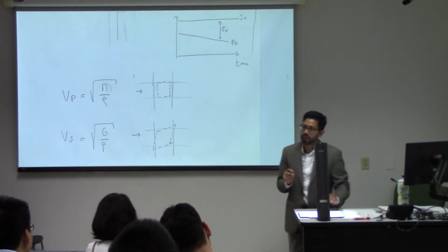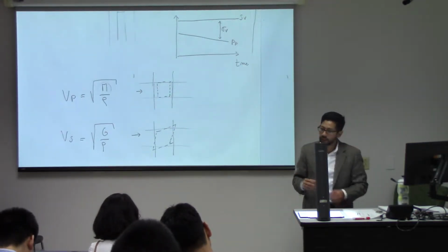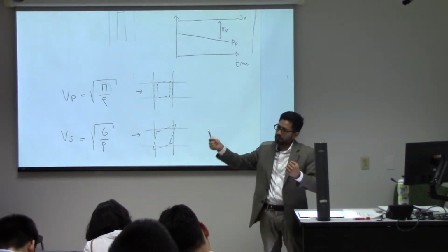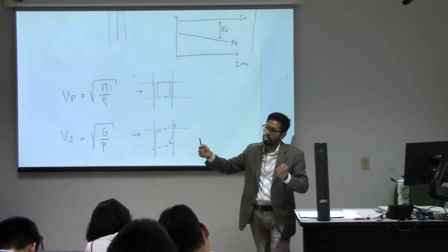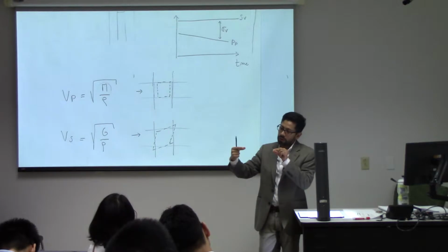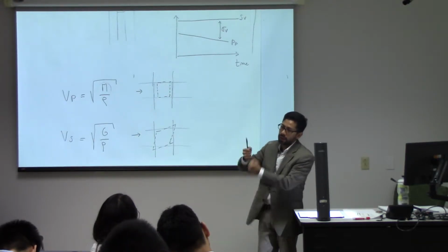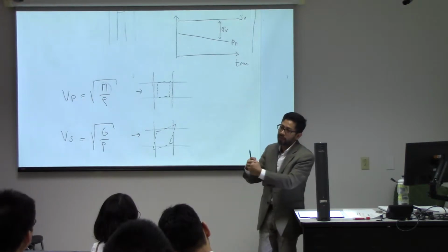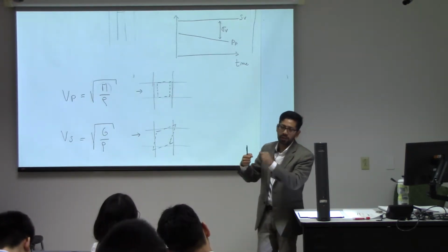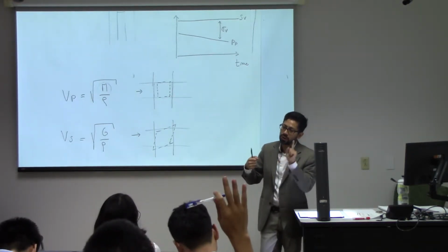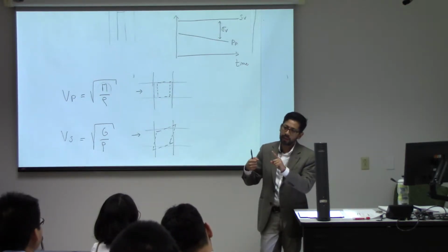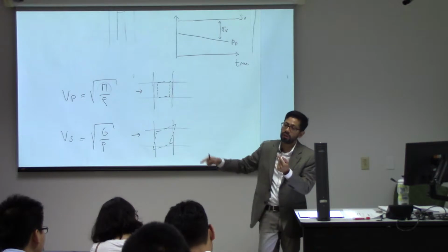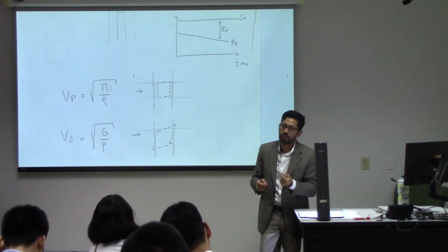That's another thing. For example, if you have a long rod that you hit with a hammer on one side, the rod is going to be able to expand to the sides, right? Like the same test that we did for measuring Poisson ratio. If it can expand to the side, that's not a P wave. It's also a longitudinal wave, but it has another velocity. Actually, that's a rod wave, and it's proportional to the Young modulus and not to the constrained modulus.